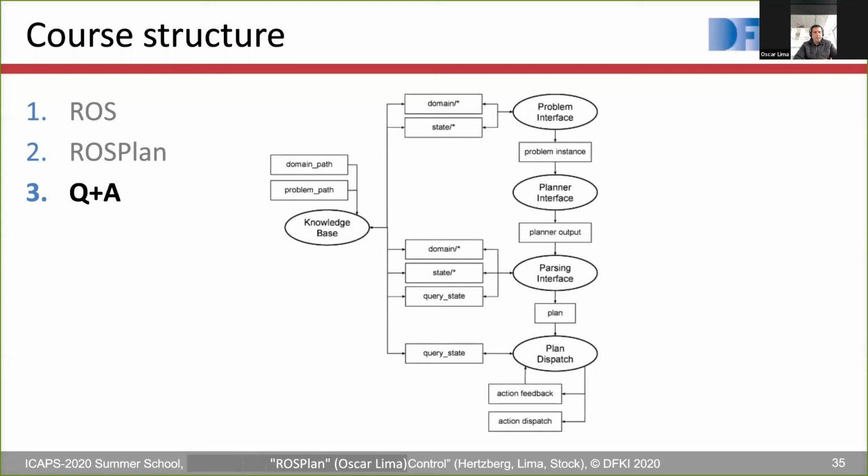And we decided to go more in favor with the parameter server. So the parameter server is a dictionary that is available in ROS, and here you can store those symbols. In fact, the Turtlebot demo is exactly what it's doing. It's just storing the symbolic poses, so WP1, WP2, the waypoints, as a string in the parameter server. And when you query this information from the parameter server, as a response, you get the pose.